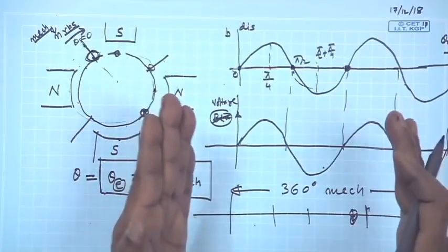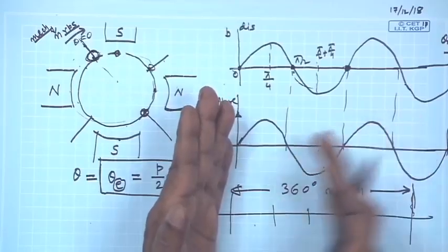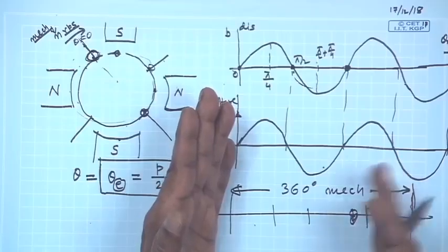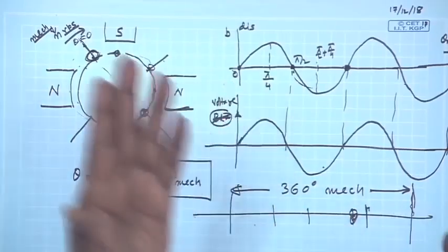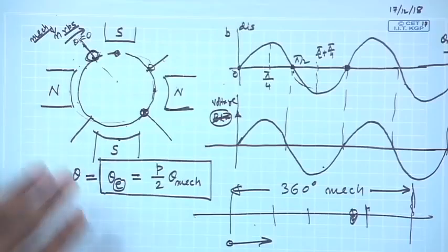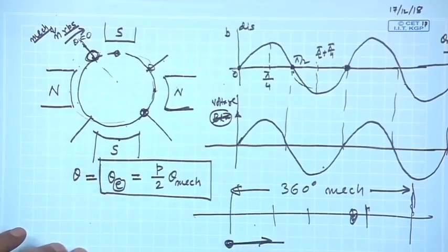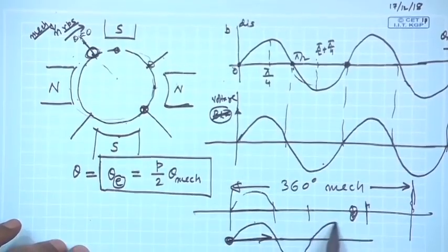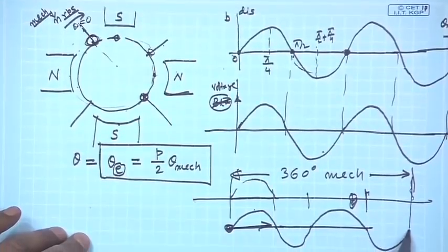That is, over the same 360-degree mechanical, I have now squeezed a pair of poles, north south, south north. And therefore, any conductor moving, he does not mind whatever you have done, but he will only see, oh, I was now under south pole, sinusoidal. So, my voltage I will make this one, then in this up it will be like this, then in this up it will be like this, and in this up it will be like this.